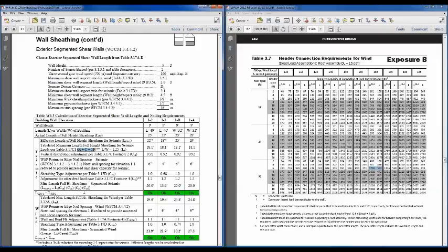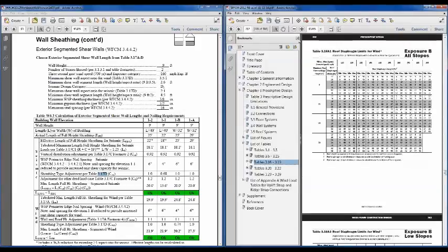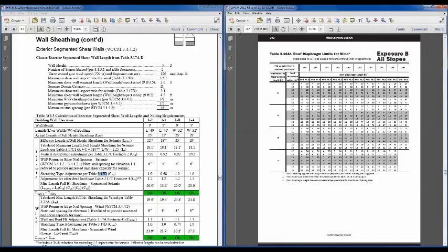And for the seismic analysis that we're looking at here, you see that when we design wall 1-1, because of those aspect ratios, those are 3.5 to 1, or sorry, 2 to 1 aspect ratios, and because we don't quite meet those aspect ratios, we've had to decrease our nail spacing to 4 inches on center to get that to work. And so let me show you from table 317D how to use that table to get that other adjustment factor to use those tighter nail spacings.